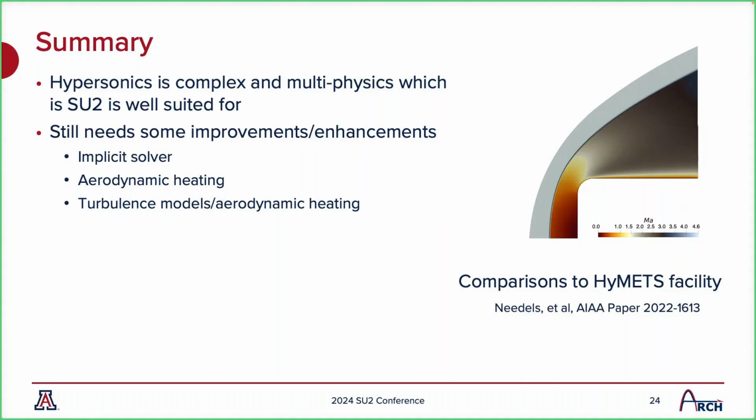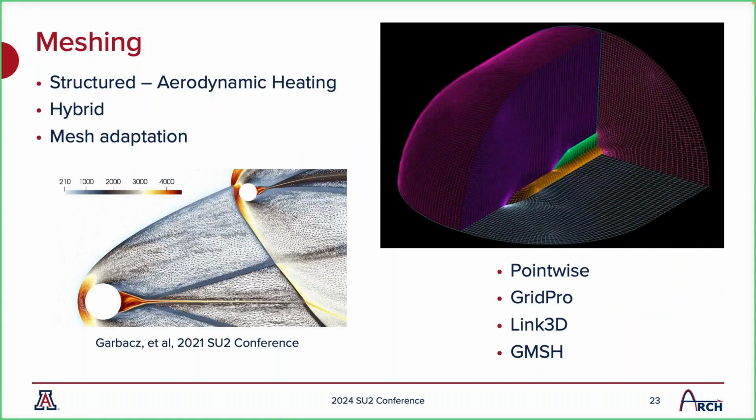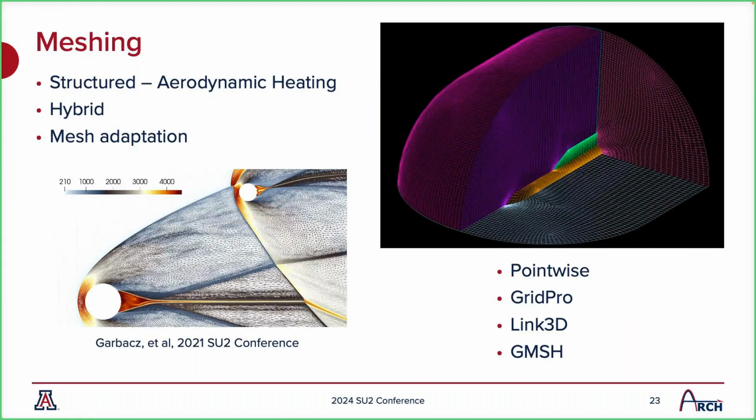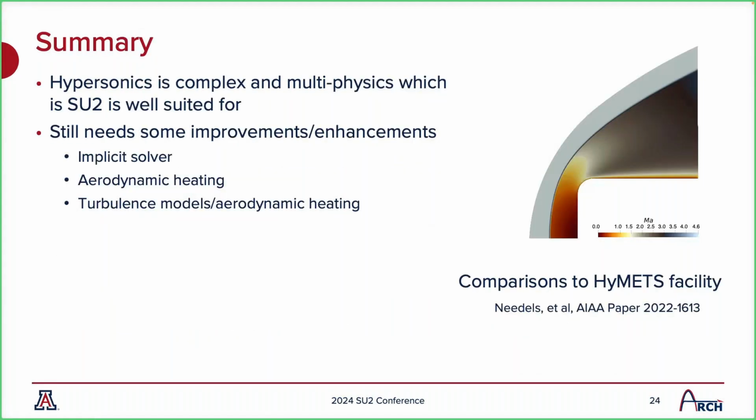It might help with the time it takes to run. But I mentioned the implicit solver here because when we have these chemical reactions, we're not able to ramp up the CFL. Usually the max CFL we can get is 1. So the implicit solver works, but we'd definitely like to improve it for the NEMO capabilities so we're not so limited in CPU power. Yeah, you'll want a higher CFL.